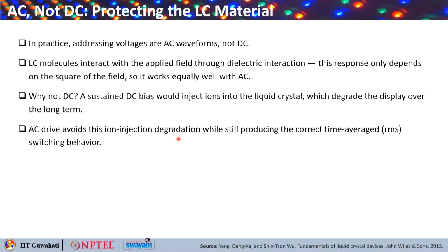So the main answer here is long term reliability: if you use a sustained DC bias, that will cause the ions within the liquid crystal material to drift and accumulate, injecting them into the bulk, and that would degrade the display's performance over time.